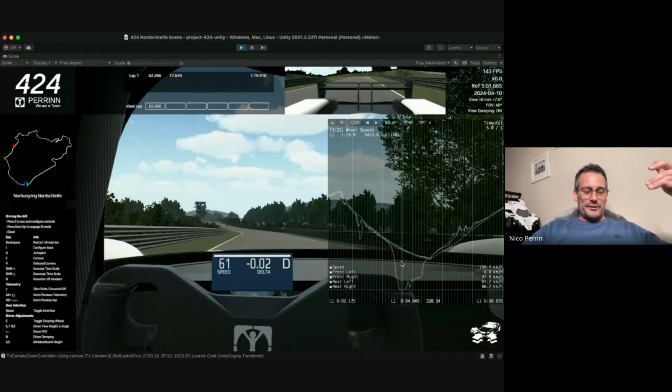And in slow speed corners, you see that quite a lot. You see that in F1, you can see the wheel stops. So these things tend to happen quite often. I would say you can still do a very fast qualifying lap even with a single front wheel lock, if you're able to bring it back fairly quickly before the apex. But the driver will still complain about it because he will feel like he had to release the brakes a bit in order to control that front wheel.